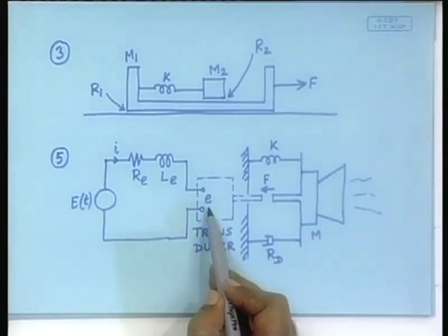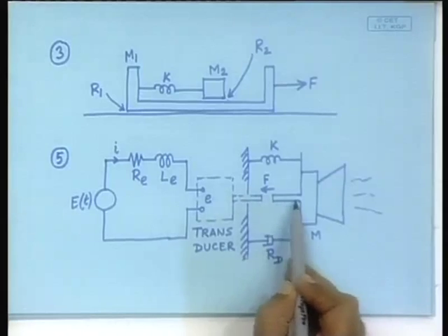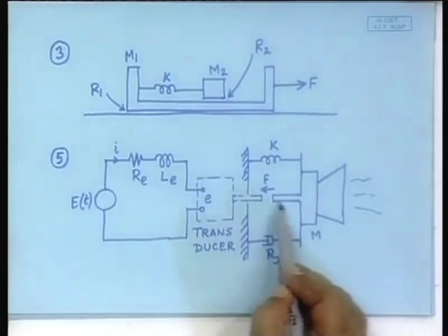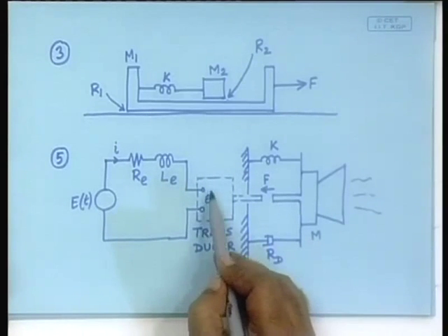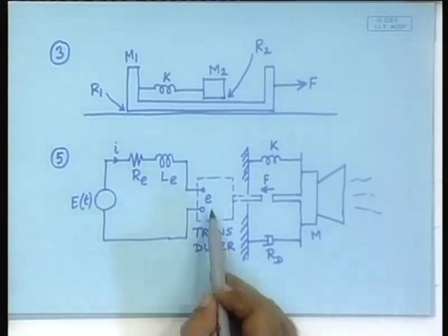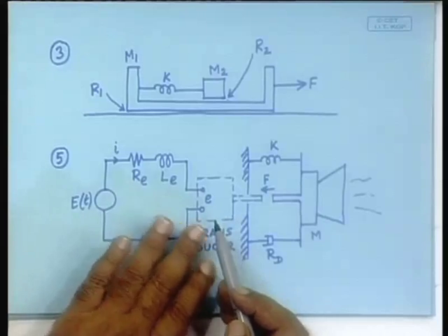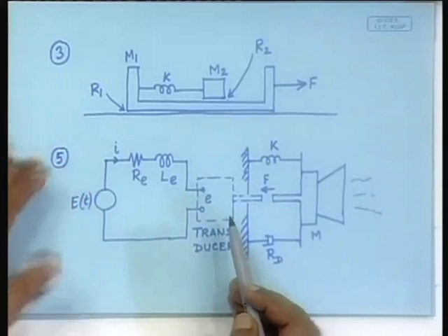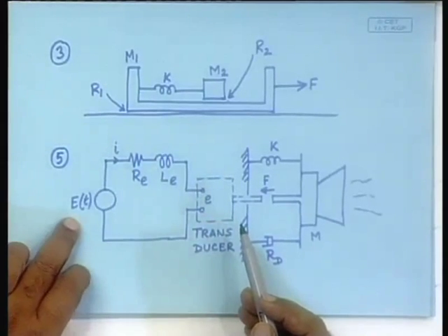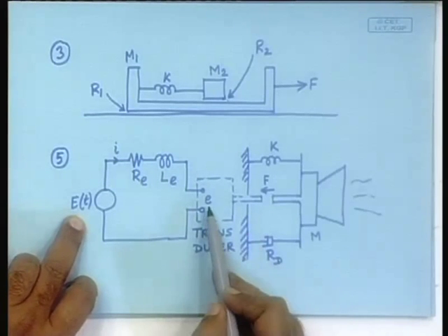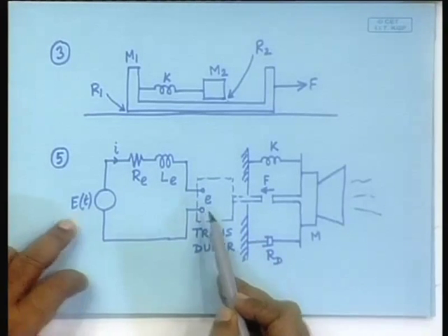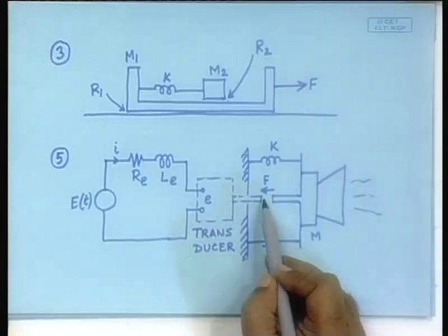So, it also applies a back EMF, because here is something magnetic going on, there is a interaction between these two, that will apply a voltage here, which will be seen as a back EMF. So, here is a voltage that is seen by the electrical subsystem. So, the total amount of voltage applied on the electrical subsystem is E minus small e, and that on the mechanical system is F.